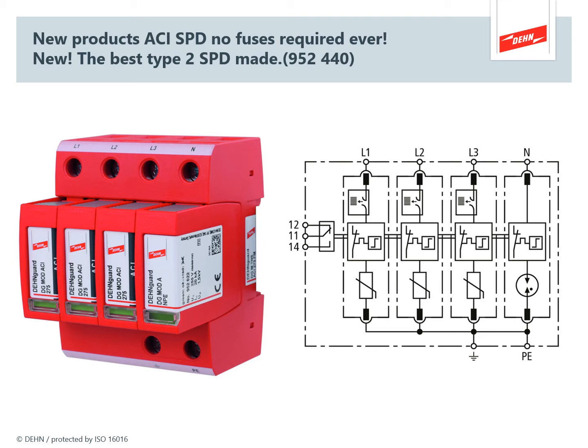The square above it is indicating the thermal disconnection feature linked to the remote changeover contact you can see there on positions 12, 11 and 14. So when we get to the point where the surge device has had enough, it'll be this part which changes the window from green to red and disconnects the SPD in normal circumstances.